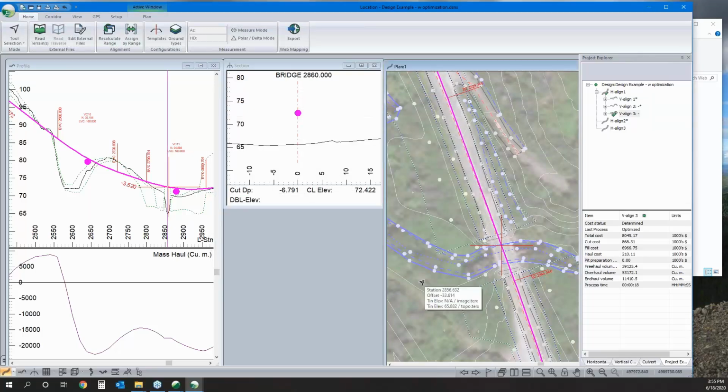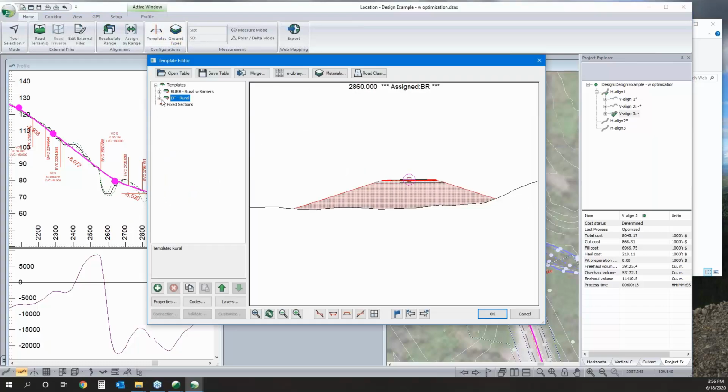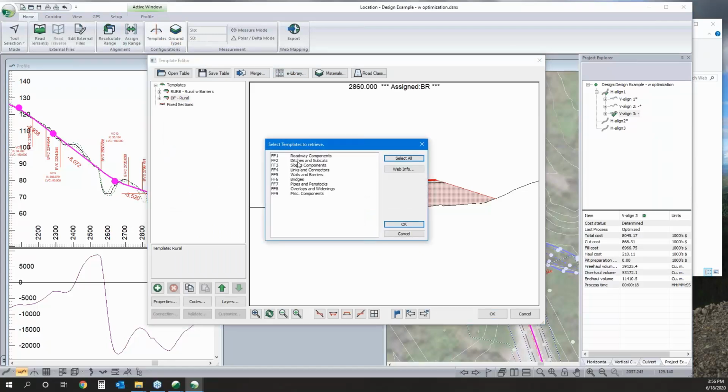All right, next question. Does the optimizer only optimize the centerline locations? By default, yes. It's undulating the centerline alignment or adjusting it horizontally, assuming a fixed cross section. I believe we're planning to do an example webinar in the future where we're using some of the version 9 features, such as using reference alignments.